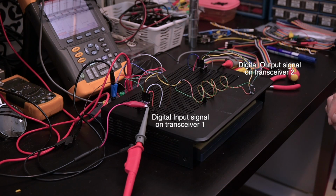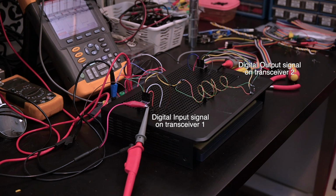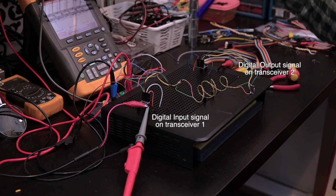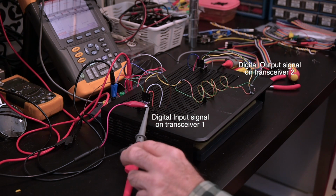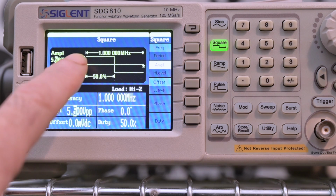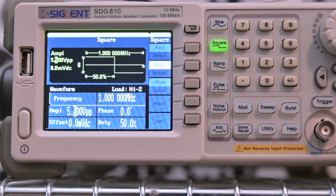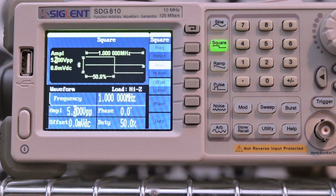This is our test scenario number 1, where we have the CAN bus wiring with the terminating resistors on it. I have my transceiver 1 and transceiver 2, all cabled up. I'm feeding transceiver number 1 with my signal from my signal generator. This is my input signal, and you can see we're sending 1 megahertz at 5 volts peak to peak, which would be the digital signal that normally your CAN controller would pass along to the transceiver.